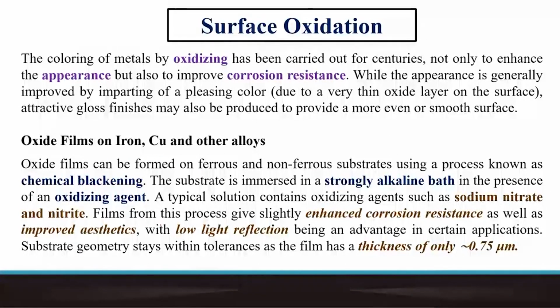When we look at a metallic surface with an inherent color, immediately we must realize that this color is because of formation of a very thin surface oxide layer, and which is an intentional oxidation. So, depending on the thickness, the defect density onto the surface and chemical nature, of course, we see various appearances of colors.